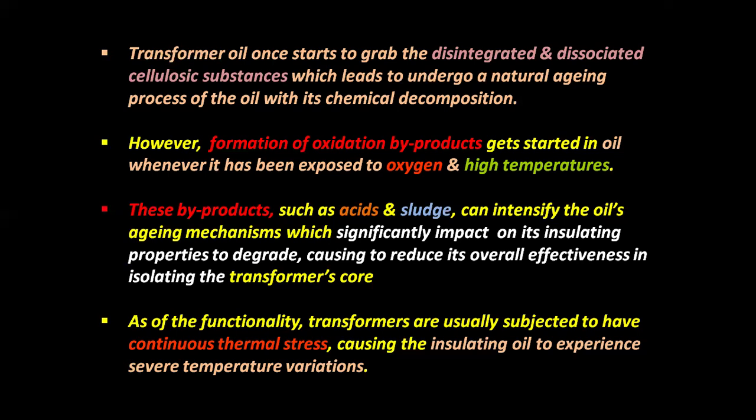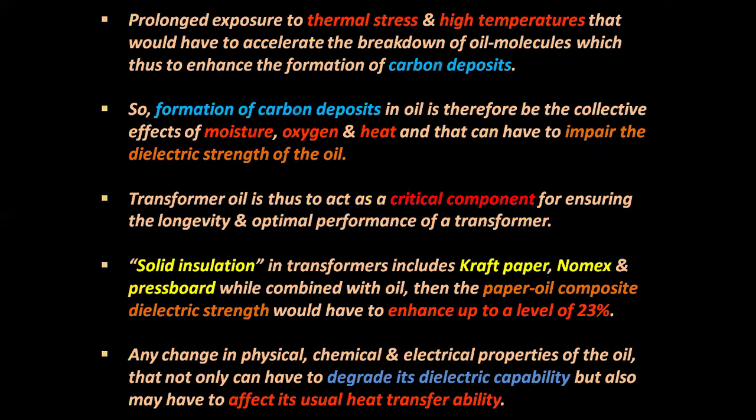In functionality, transformers are usually subjected to continuous thermal stress, causing the insulating oil to experience severe temperature variations. Prolonged exposure to thermal stress and high temperatures accelerates the breakdown of oil molecules, which enhances the formation of carbon deposits.